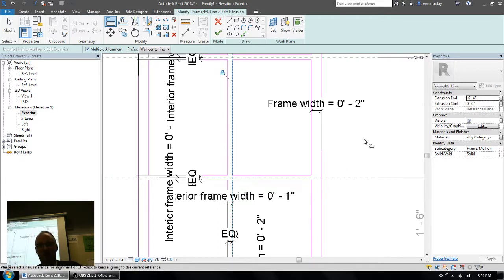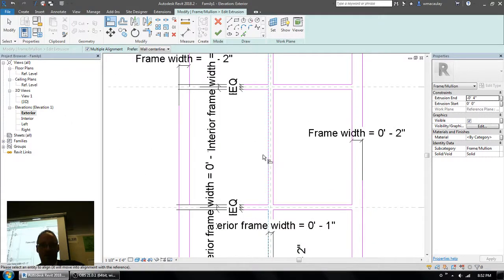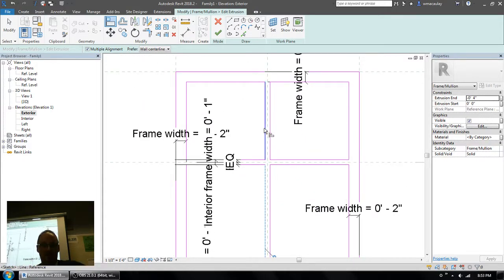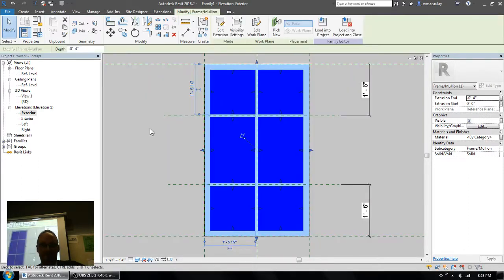Because I've got the multiple option going here, I need to reset my point of reference, so I need to find some white space. I go to the other side, find the sketch line with the dimension on it. It's not picking the sketch line, so I have to hit the tab key just once. There we go. And now I can click it, and that's my point of reference. I can pick the next sketch line here, unlock it, and the next one, and lock it. Normally I'd make sure I'd done them all before I finish, but just for the sake of time, I'll finish it now.